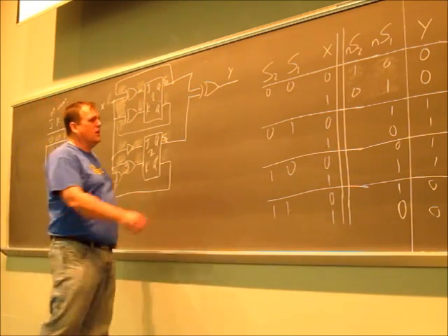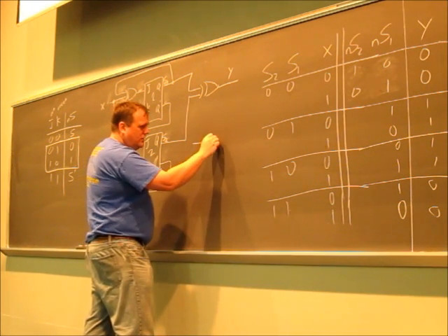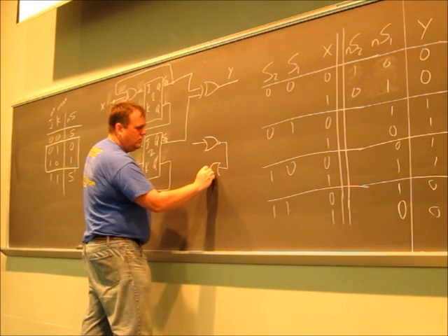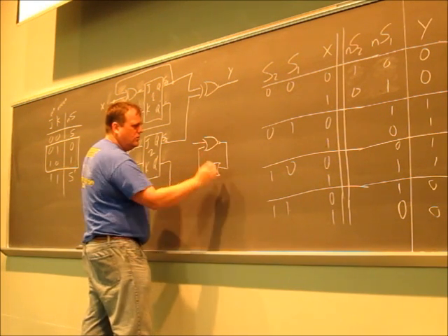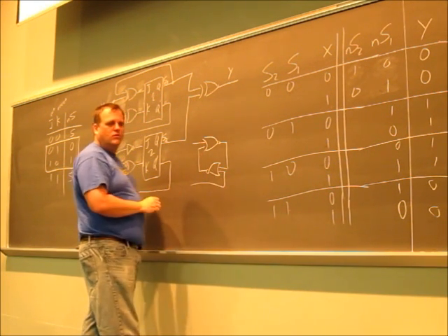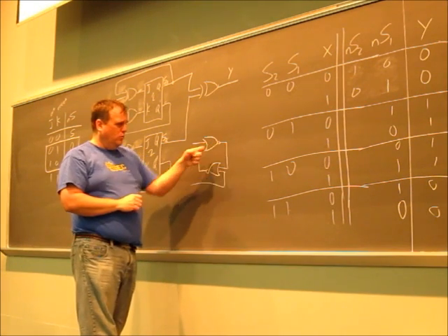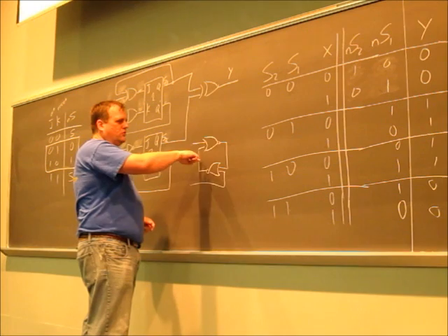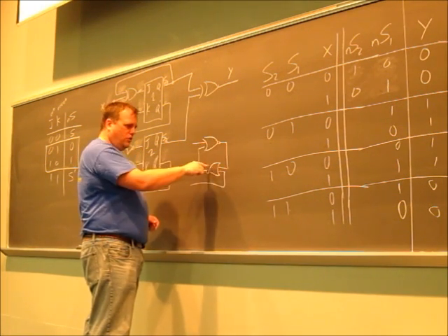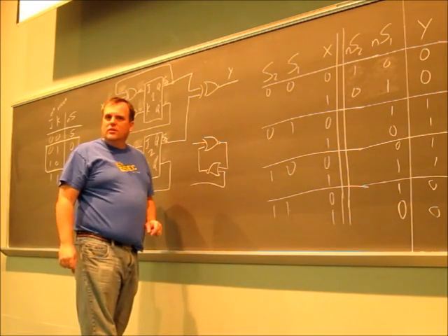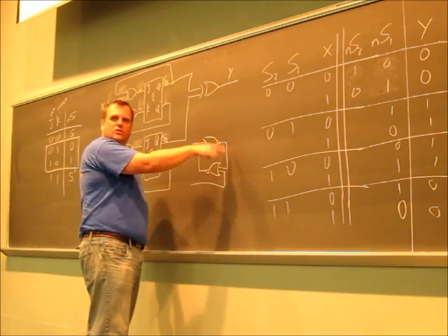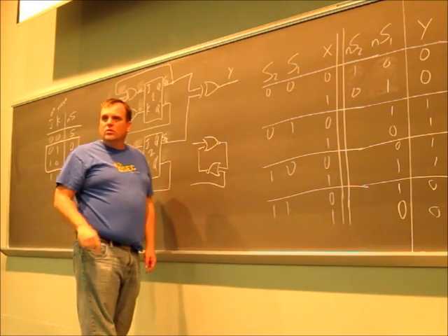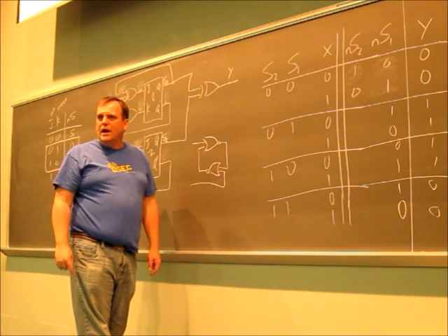Realize inside this, I actually have those NOR gates feeding into each other. So I've got Q and Q prime. They're not separated from each other, because Q prime goes into Q and Q goes into Q prime. That's how we were getting memory, their signals coming through, and these are both powered, so they maintain the state by their power.